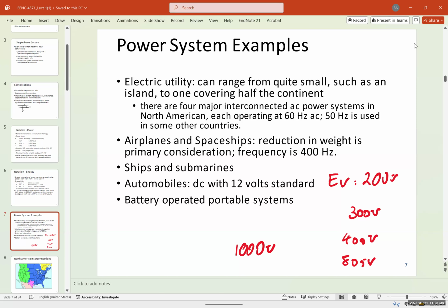So the thing is, it depends on the output voltage again, and it's not just about the frequency. It's about the output voltage, input voltage, and how much output current you are drawing. But up to 2-3 kilohertz, from 2 hertz to 3 kilohertz, it's not a problem with these transistors and switches. Anything above a few megahertz is going to be difficult.